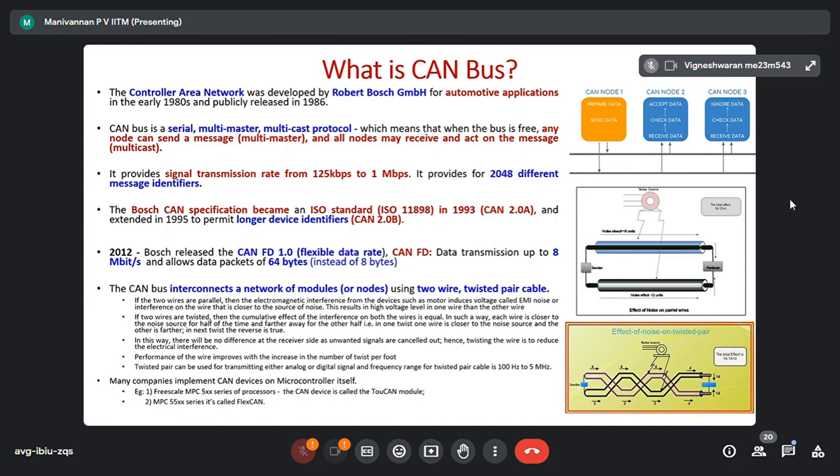But in the case of CAN bus, that is not good for every possible communication. In the case of vehicle control, when you apply the brake, even though the engine is running under a separate controller, the ABS ECU becomes a master, because it has to tell the engine ECU to stop the engine or reduce the fuel, decelerate. I am going to apply the brake. So at that time this has to become master, and the others should become slaves.